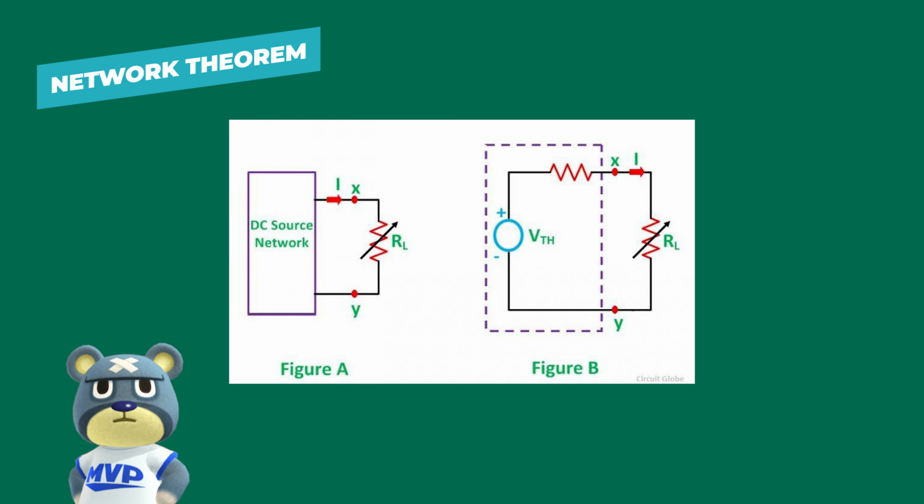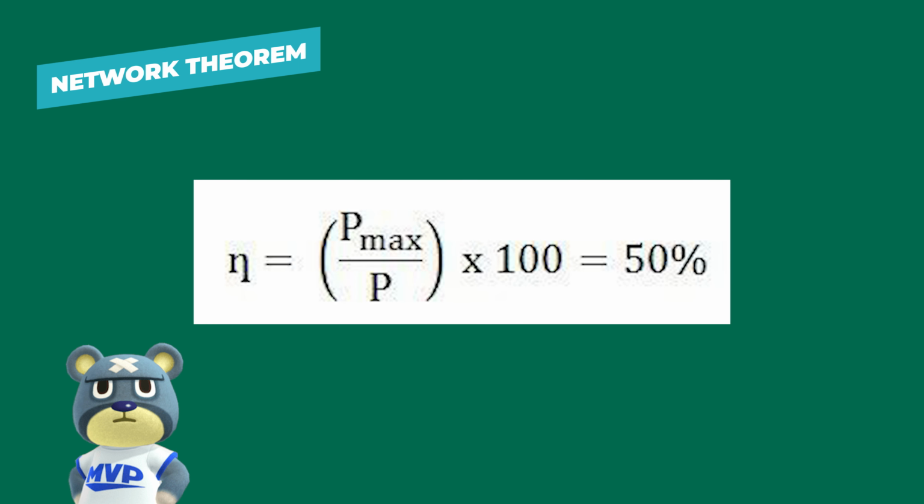This has wide application in communication circuits, where the magnitude of power transferred is sufficiently small. To achieve maximum power transfer, the source and the load resistance are matched, and with this the efficiency becomes 50% with the flow of maximum power from the source to the load.